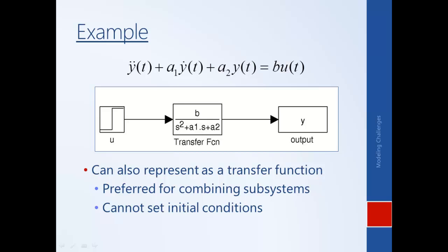We also need to be aware of the fact that this transfer function doesn't capture the initial conditions of the system. When we found the transfer function, we assumed that the initial conditions were zero. Furthermore, we cannot represent nonlinearities. So the Laplace transform of a nonlinear function of y can't be performed. So this gives you some ideas of when you may want to choose a differential equation model and when you may want to choose a Laplace transform or transfer function model.